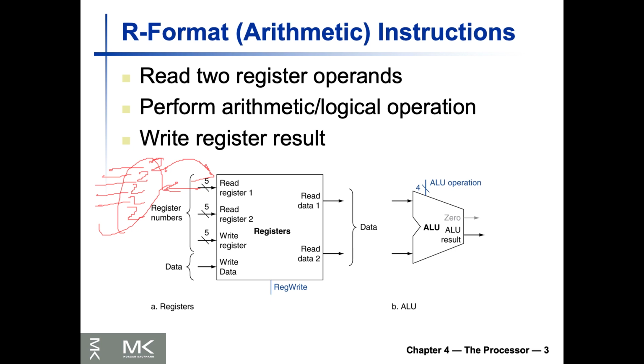And we mentioned that the register file is always going to output the contents of the registers corresponding to the read registers, right? For the read registers, we don't need a read control wire, just like what we have for the write. But for the write, because we are trying to write data, we need another control signal that sets the write on while we are writing.